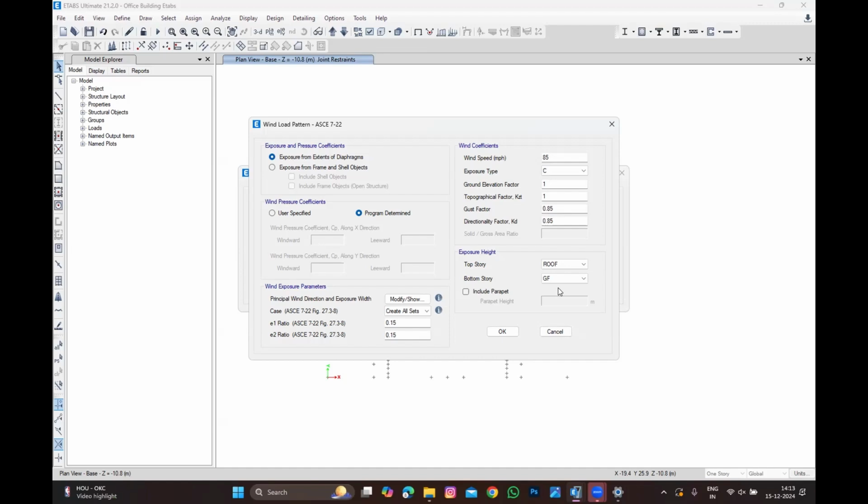Because the dowel bars come from the slabs, what will happen? The additional 1.2 meters, when the lateral force is acting, creates additional moment. Now I'm considering the height till the roof, right? Say for example it will be 60 meters, so my parapet is 1.5 meters, then I need to consider 61.5. Then wind will be a little more. Usually we avoid this 1.2, 1.5 meters, mostly because we consider they will go for block wall. If you decided otherwise, then it comes from the dowel. Even for 1.2, you have to consider it.